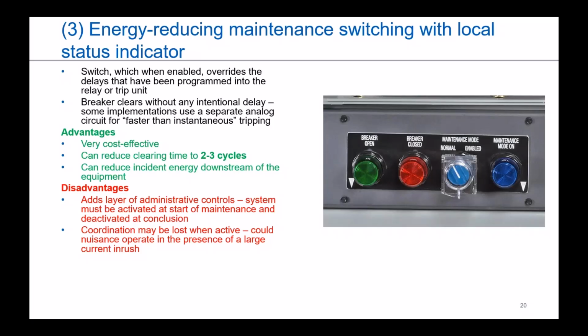The other drawback to it is you can sometimes lose coordination. So if you've got a selectively coordinated system, depending on what's going on with the person being in front of the equipment, you could potentially get some nuisance operations and tripping some things further upstream than was really necessary, if for some reason you experienced a large amount of inrush while you're in front of the gear doing the testing.